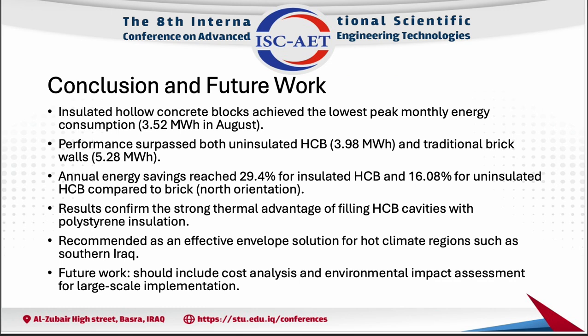Now let's move on to the conclusion and the future work. Based on the simulation, the insulated hollow concrete block system achieved the lowest peak energy consumption, which equals 3.52 megawatt hour in August, compared to 3.89 megawatt hour for uninsulated HCB and 5.28 megawatt hour for the traditional brick wall.